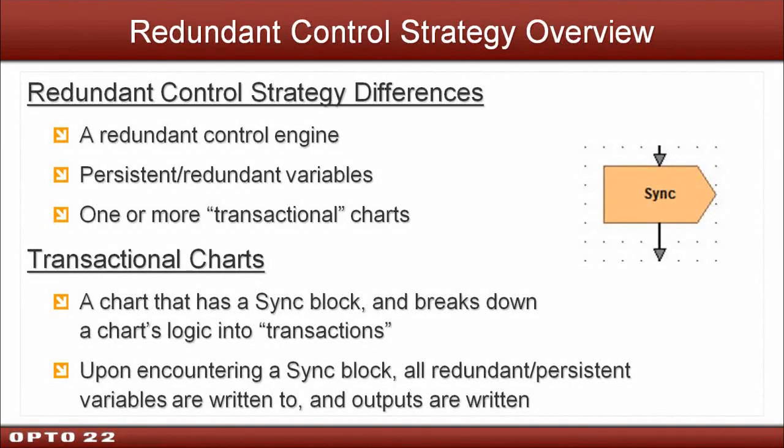Okay, so what's a transactional chart? As you know, and different than, say, a PLC, a PAC Control and a controller, when it's communicating to I/O or variables, when it encounters a command to do a write or to write to a variable or write to I/O, whatever, it does it immediately, as opposed to, say, a PLC, which scans inputs, solves logic, then sets outputs. So what a transactional chart does is essentially bring a scan, solve, set to a chart. In other words, creating small transactions within a chart.